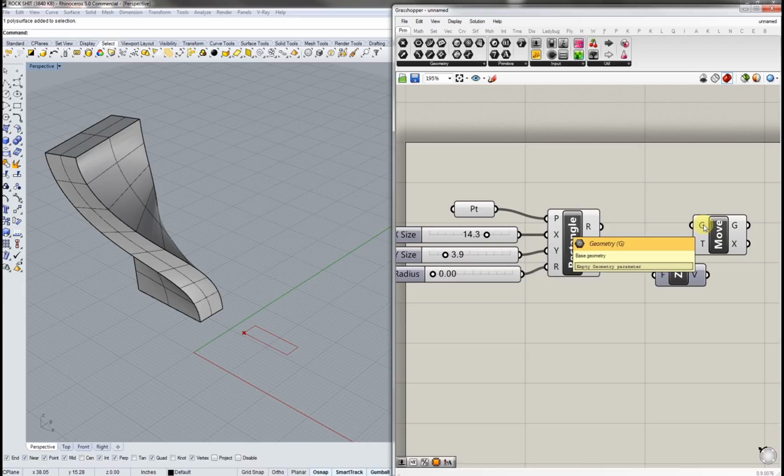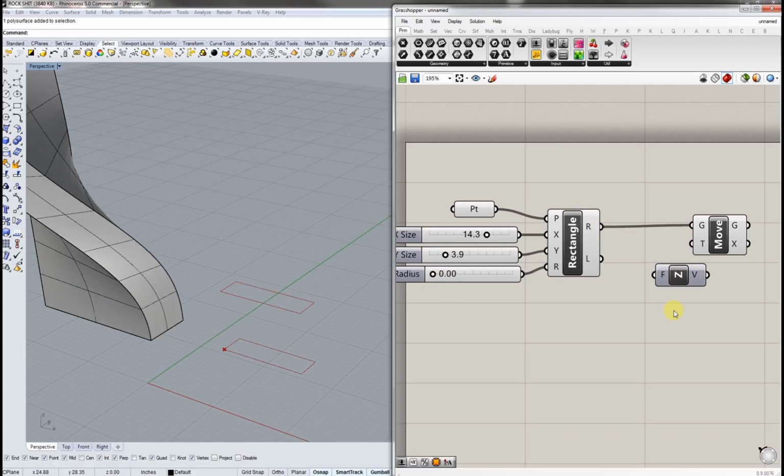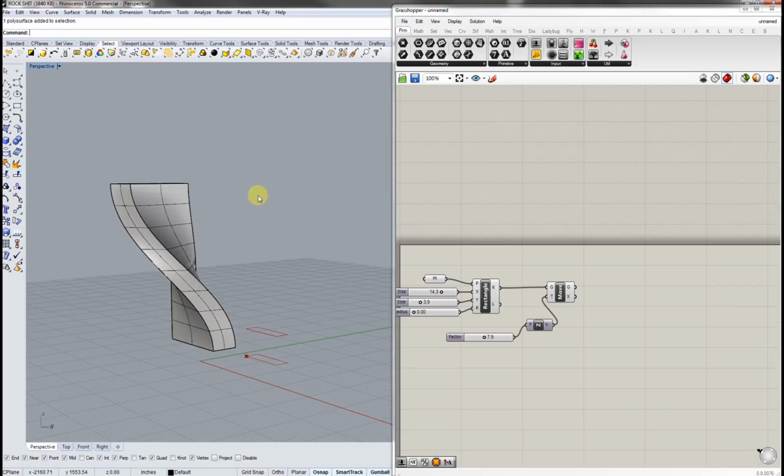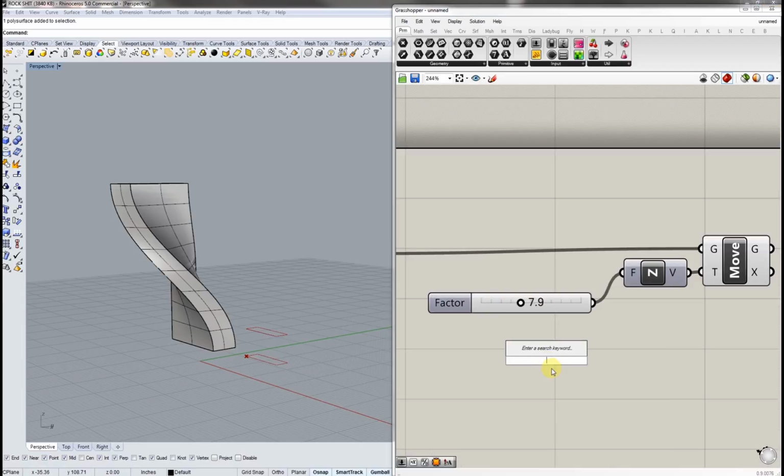Great. So what we're going to do today is something similar to this. If I build this in Rhino and I put a twist on it, we can start to twist objects in Rhino, for instance. But if we wanted to twist them exactly to a certain parameter and we wanted multiple iterations, well, it's a little bit tricky and a little bit redundant. So what we're going to do is loft a bunch of surfaces up to create something similar to this and also be able to generate different iterations of that movement. So for the next step with this rectangle, we're going to move it up.